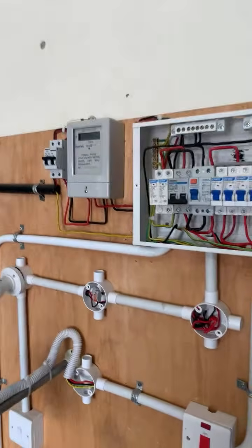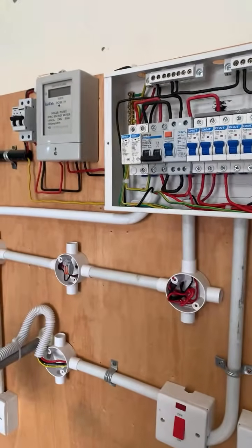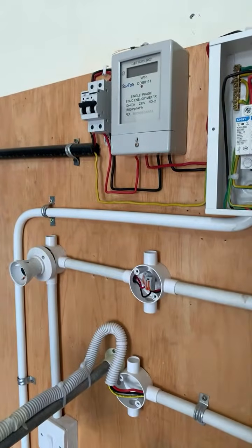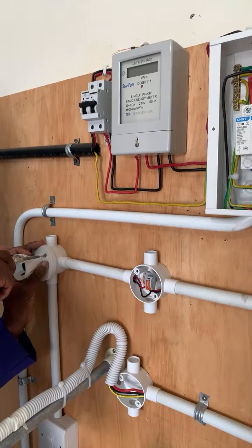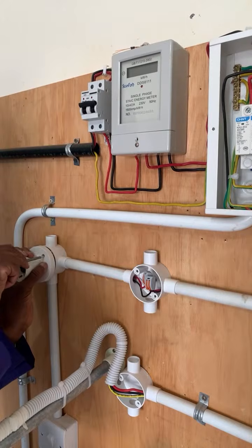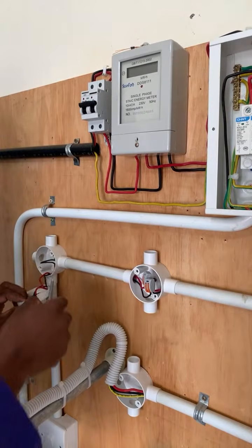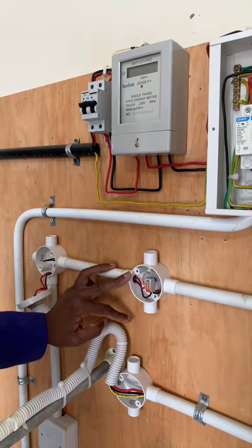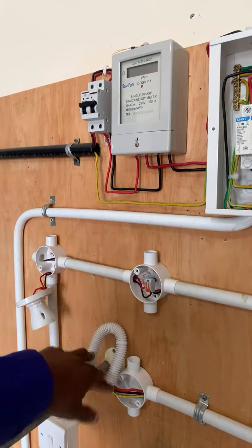There are important factors that you need to factor in when you are conducting electrical work. For instance, resistance. That is another area that so many people have a challenge with. Another indication that you will know that this person does not understand much about electrical installation is the fact that they will not factor in resistance. And how does the resistance come into play? It comes into play in this sense: the choice of the size of cables.